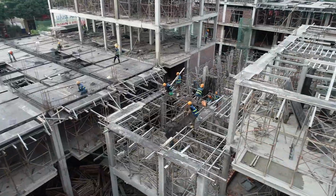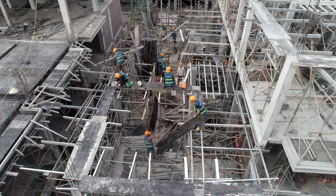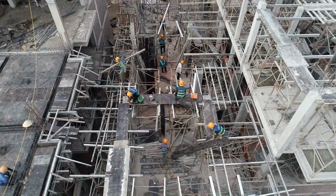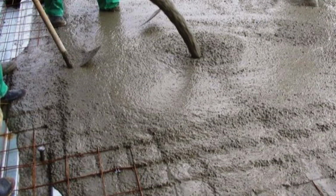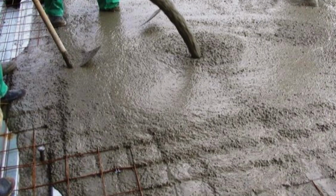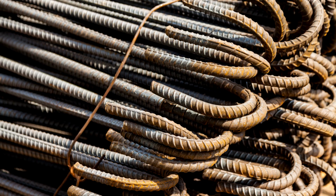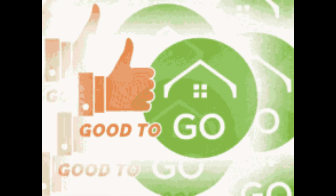Before signing off the concrete, we have to remove the foreign materials from the formwork and then confirm the alignment of vertical and horizontal elements. The contractor or the site engineer has to provide the test results for all the materials used, including concrete grade and steel tensile strength test. Once we check all these points at site, we are good to go for the concreting.